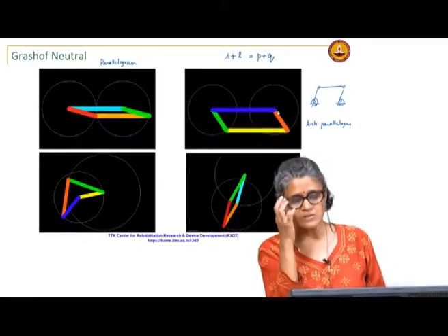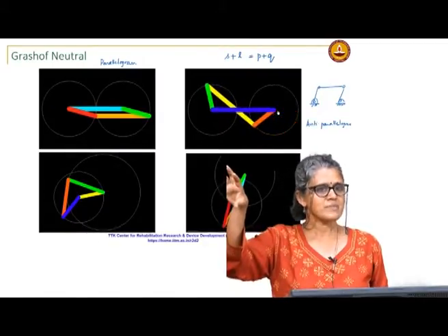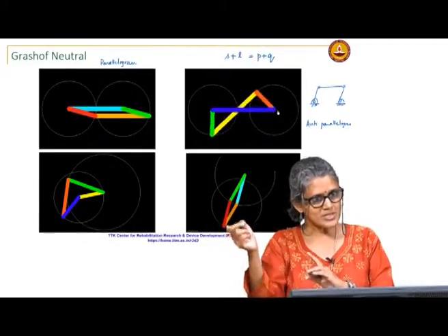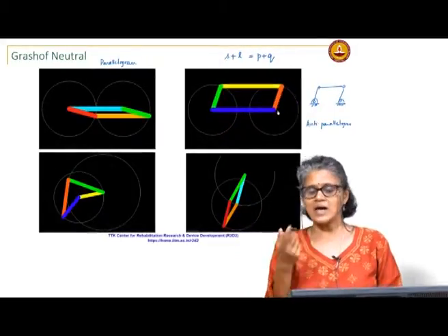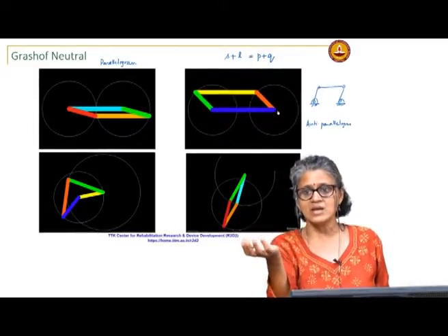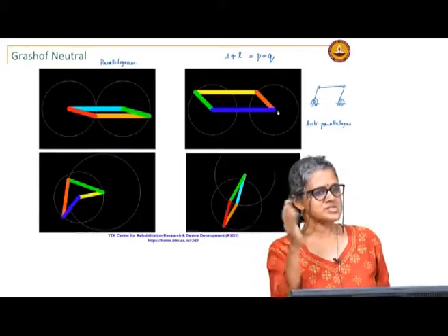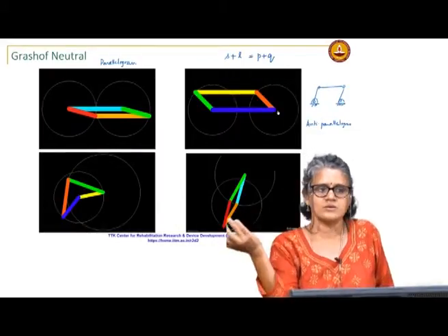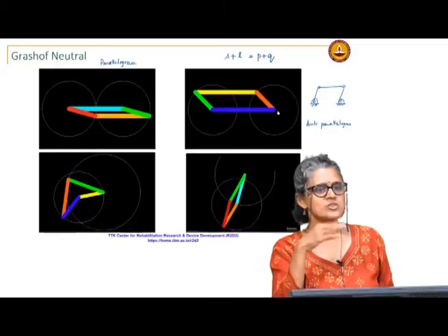There are a couple of ways of dealing with that. One is you put another parallelogram mechanism that is out of phase with this, so that when one is at the change point, the other one is not, so it drives it in the direction that you want. The other thing is, do not run it over the entire range. You may not need to run every mechanism over the entire range of motion. So, if you need the parallelogram action only in, say, a rocker fashion, you are perfectly justified in using that between those limits.